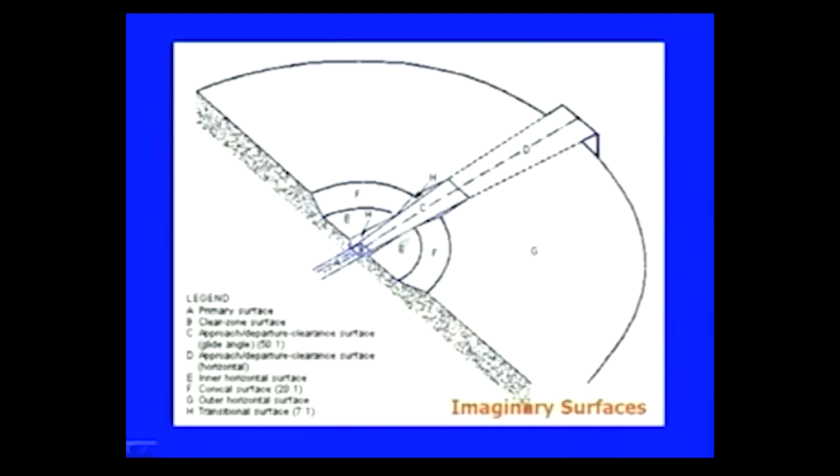So, that is a trapezoid form going upward, as well as becoming wider as we go away. This is 15,000 meters on horizontal, and at this point the height will be 300 meters, and then at 12.5% rate it is coming outwards in this direction and in this direction.